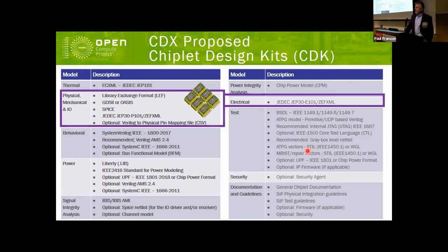We're also asking for a SPICE netlist. This would be a top level black box SPICE netlist that could be used for SiP level LVS. And then the next group are the mechanical views. So these mechanical views provide more package-centric information that would be useful for package assembly.